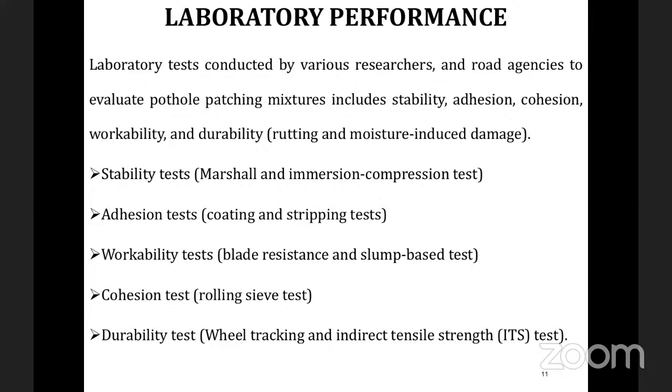For stability, normal Marshall and immersion compression test or ITS test, that is indirect tensile strength, we can also go for. Next comes the workability. In workability, we can go for blade resistance or slump based test. That is the normal test which the Department of Transportation in Texas or Virginia have developed.